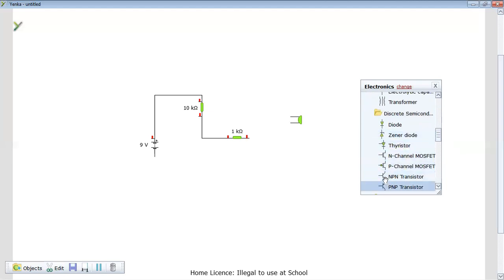And down here, there's two types. You'll notice one of them has an arrow down, which is the same as our diagram. So we want this one here, NPN. Sometimes you just got to scroll through the different folders to find the component you want, but these electronic symbols should be quite familiar to you right now. You should have been able to recognize this one here. We've done it a few times in our electronics lessons. I'm going to now connect. Oh, I hate when it does that. Sometimes it struggles a little bit. There we go. With drawing the lines, you just got to move it backwards and forwards. So we've got our two resistors there, our buzzer up here, and then that was our transistor down there.